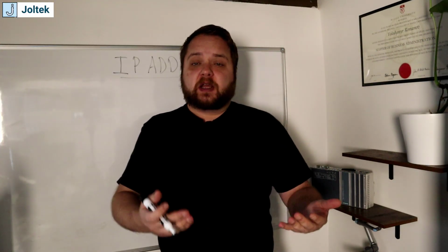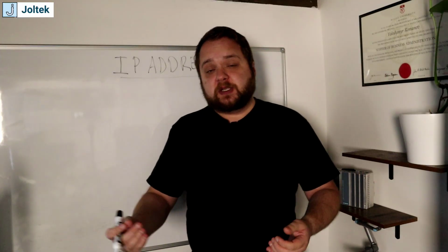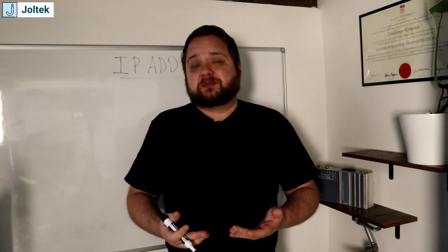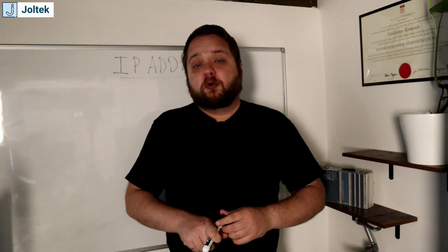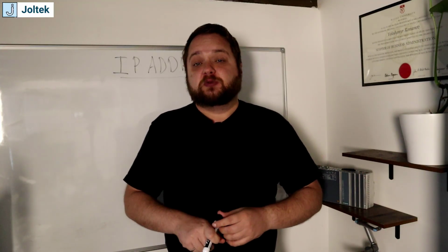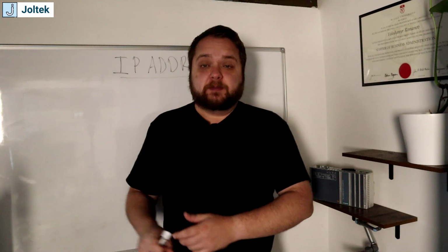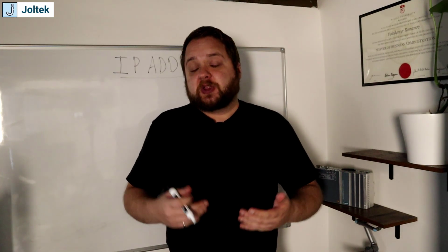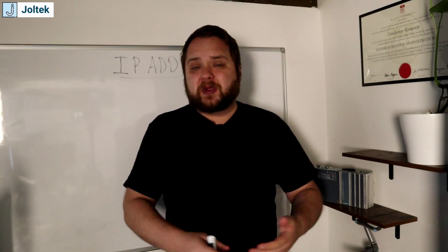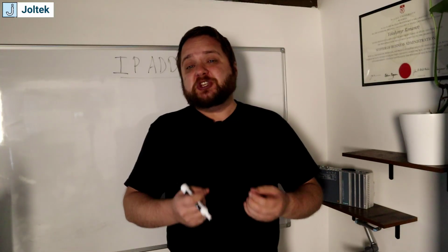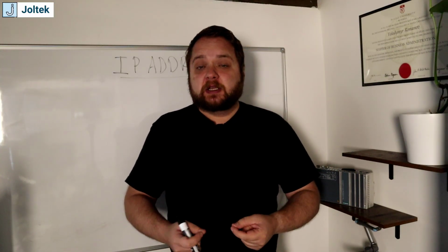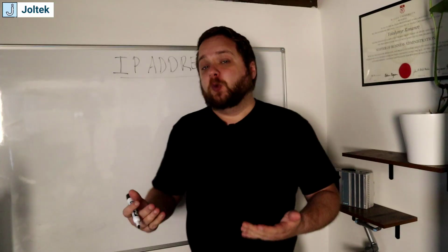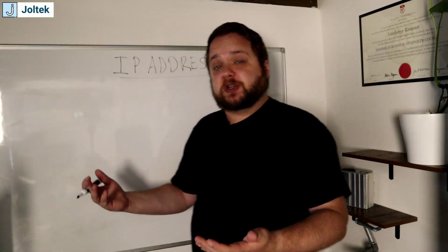As we connected our laptop to the VFD, we were able to ping it, but that's basically just a check for being able to communicate between the laptop and the VFD. In order to pass information, that's going to take a little bit more programming, a little bit more software, but you need to know the address of the device that you're communicating with. And that is where the IP addresses come in.